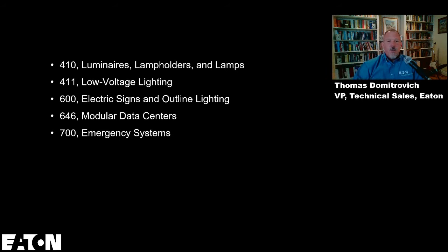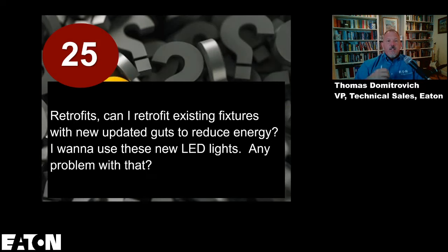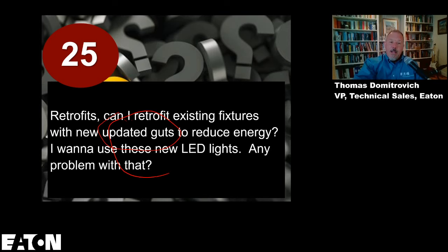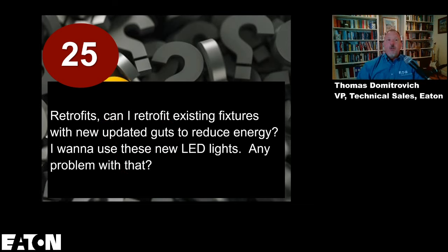So, in regard to that question on retrofits: can I retrofit existing fixtures with upgraded guts to reduce the energy? The upgraded guts, I would call those retrofit kits, and apply them within their listing and rating. So yes, you can do that. There shouldn't be any problem as long as it's a listed product and it's applied appropriately.